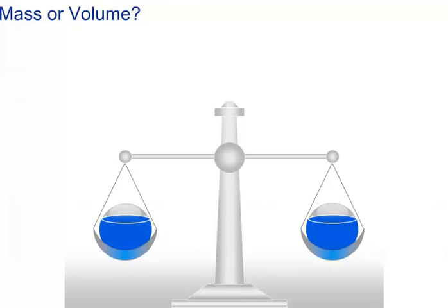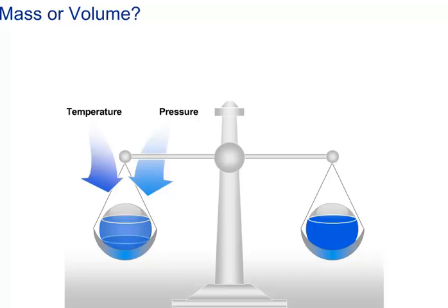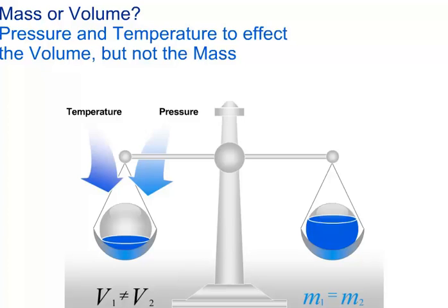The main advantage of Coriolis meters is the fact that whilst pressure and temperature may affect the volume of a given liquid, they have absolutely no effect on its mass. This metering principle is therefore independent of pressure and temperature changes. Since the meter does not require any conductivity of the medium for it to function correctly, it is one of the most flexible flow measurement principles which can be found in modern-day process measurement.